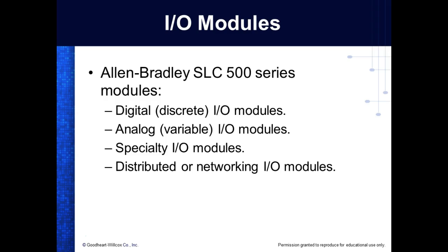Specialty modules. So we can get current loop modules. We can get, I said, like Ethernet modules. We can get all these different modules besides IO modules. But when you try to program them, you've got to tell the application exactly what you have out there, right? You understand? Because, like I said, RSLogix 500 is capable of programming all of the Allen Bradley PLCs all the way up to their CompactLogix line. So you've got to be able to say, okay, I've got this CPU, right? You understand? I've got this type of module, and that kind of stuff.